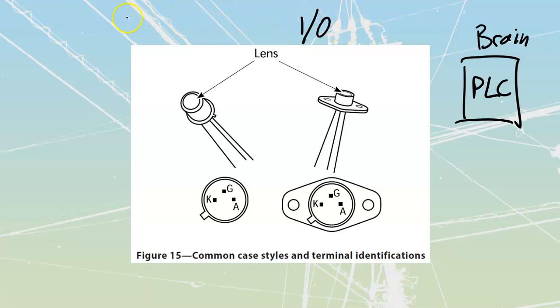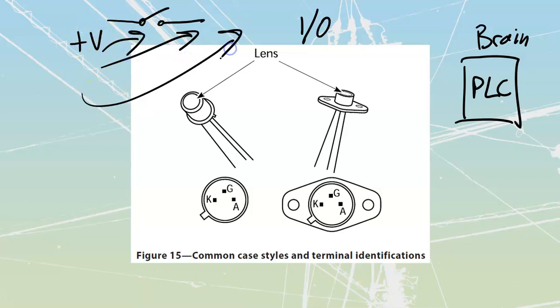That I/O is going to be coming in from electricians' carry field wiring. So you guys are out there doing who knows what. Here's some voltage, we'll just apply that over here. I don't know, we'll just attach to this terminal over here. You do all this crazy stuff to our I/O cards, and sometimes you screw it up, okay? And when you screw it up, we don't want your electrical screw-ups. Let's say you took 600 volts and attached it to a 24-volt card. We don't want all of that 600 volts to travel through and affect the brain of the PLC, because that's going to screw the entire thing. We'd rather that you just blow up the I/O card.